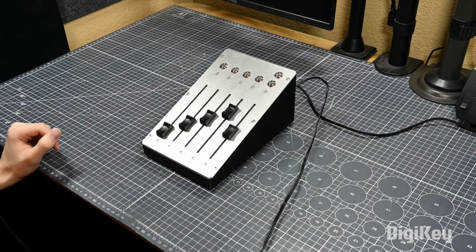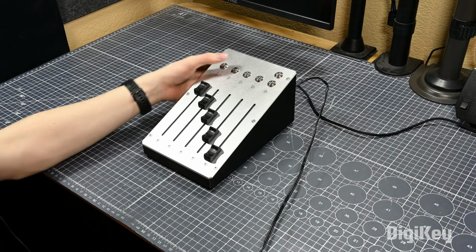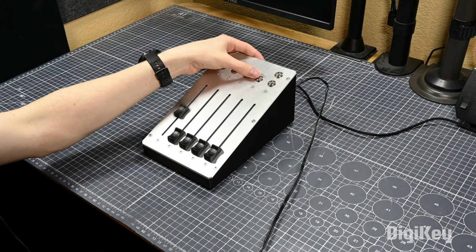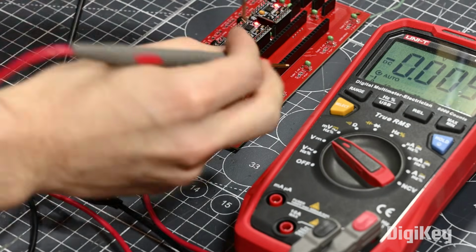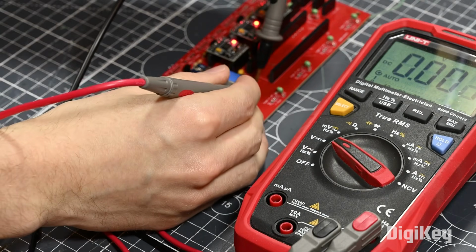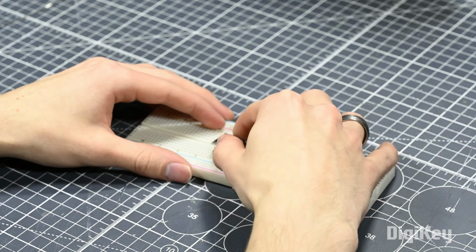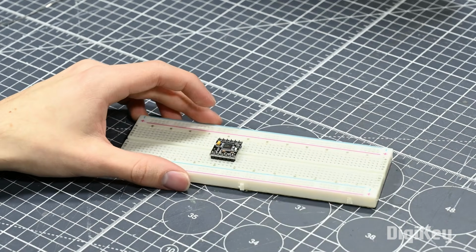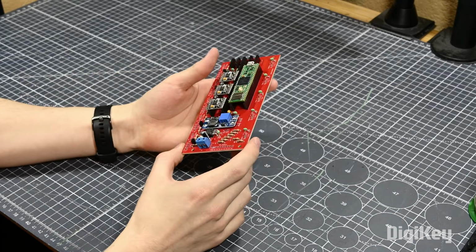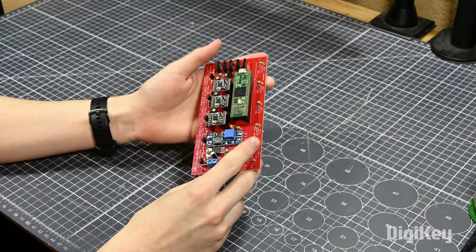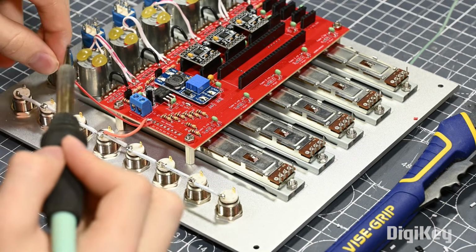What's interesting to me is that these are the exact same faders he used in a previous version of this project where the motion was slower and a little clunky. The difference is the type of motor driver used to power the motors. This latest version uses DRV8833 modules, which are FET-based and can handle more current. That's paired up with the Teensy, which has a fast processor ideal for the PID control loop needed to accurately move these things in and out of position. The result looks super professional.